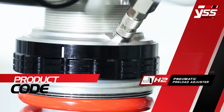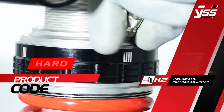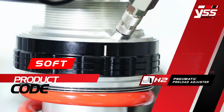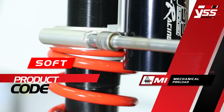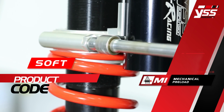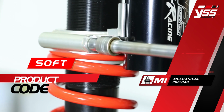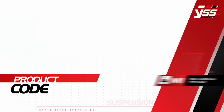H2: Pneumatic preload adjuster. This preload adjuster works by using hydraulic pressure from a gas canister to press the spring, which can turn the knob to adjust the preload spring by hand. M1: Mechanical preload. Adjust the spring mechanism by worm gear. This type is designed for enduro or motocross, which uses spanner wrench number 8 to adjust.